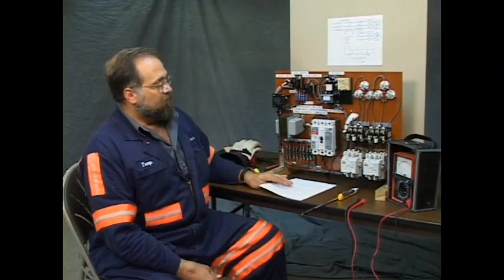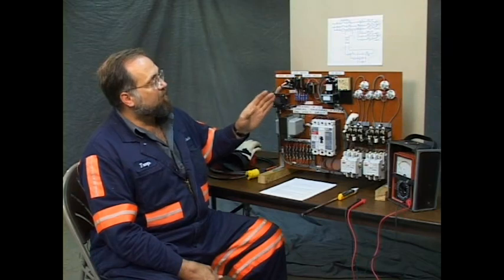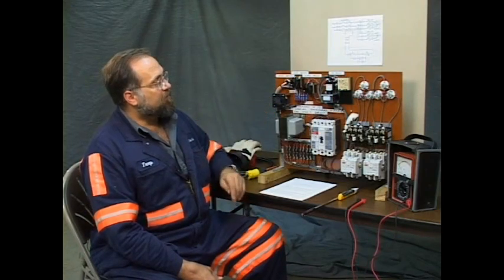If you remember from running the panel with no problem at all, the sequence of events: A contactor goes immediately when you press the start button, and after the time delay, B contactor goes. Purpose in the time. Should this circuit be controlling, say, 2 large induction motors?